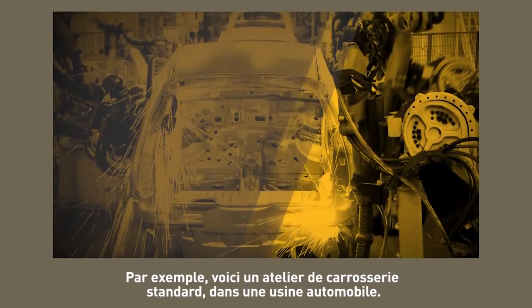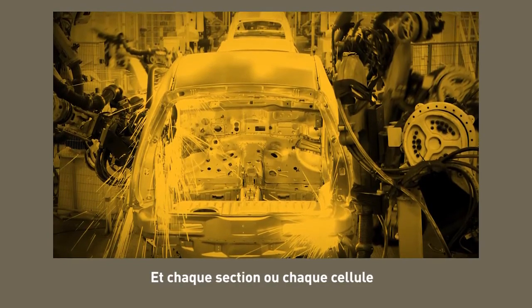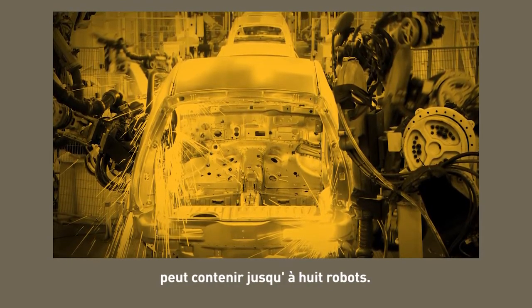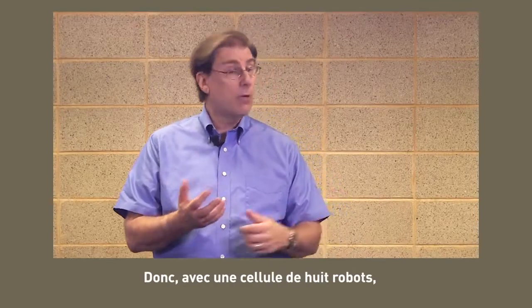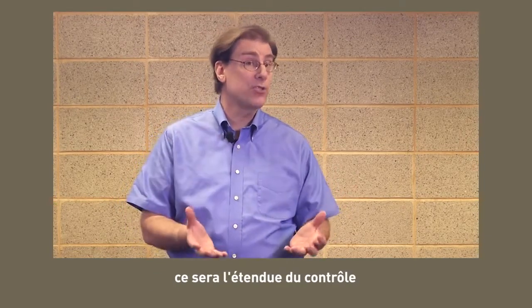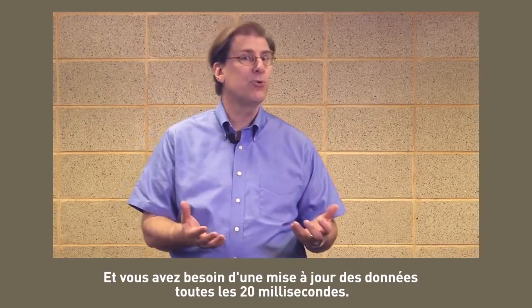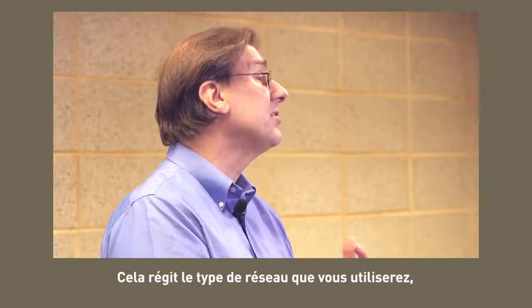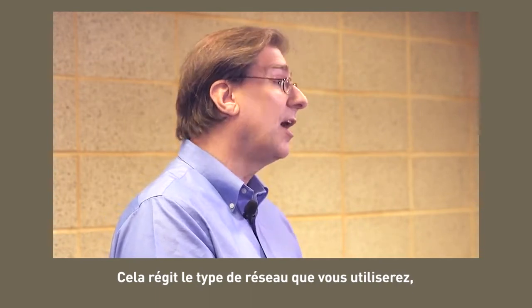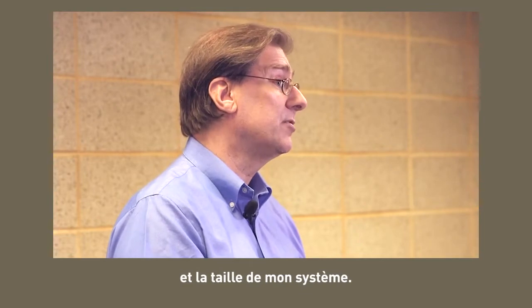This is a standard body shop in an automotive factory, and each section or each cell may contain up to 8 robots. So it would be an 8-robot cell, probably about 400 I/O points, and that would be a typical span of control. How many I/O points, and you need data updating at about every 20 milliseconds. That kind of governs the type of network you're using, how fast the data has to get there, and how big my system usually is.